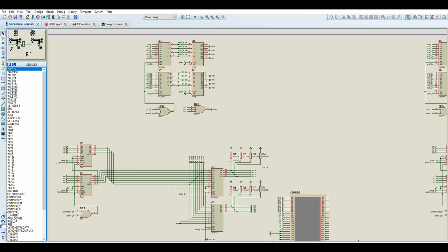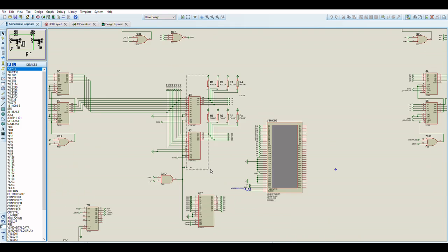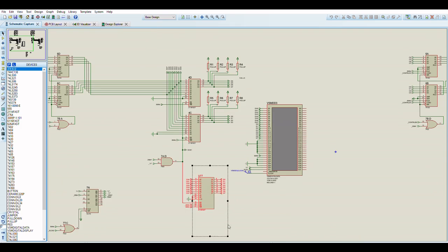So blank in the scanline RAM is FF, and then values are stamped into that, and then it's inverted on the way out, which is, like I said, a really cool way of working. It's very, very efficient. It's also extremely taxing on the memory. These memory chips have to be extremely quick on flipping over between reading and writing. Luckily, they are really good at it.